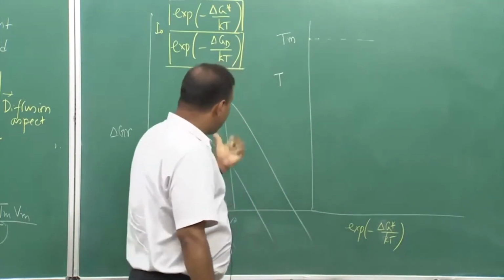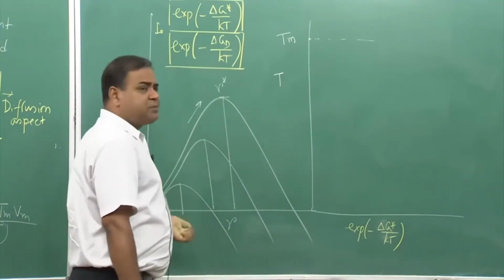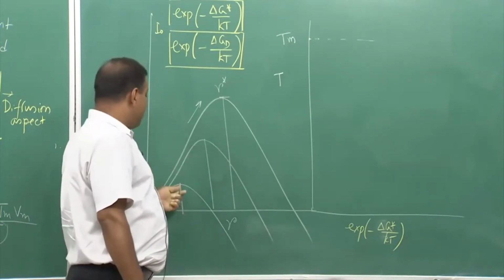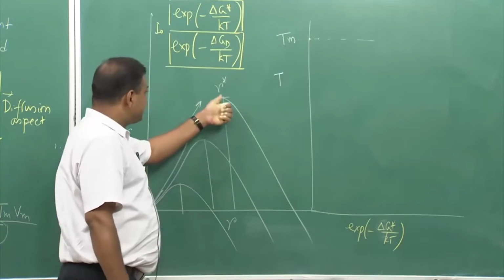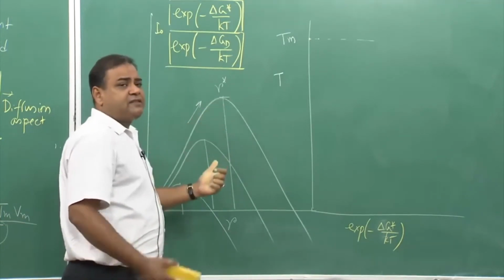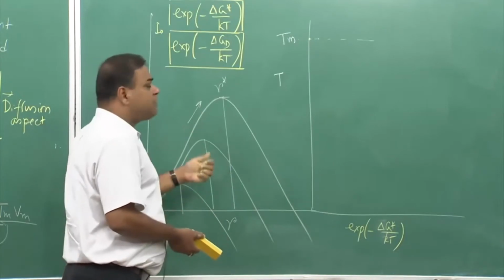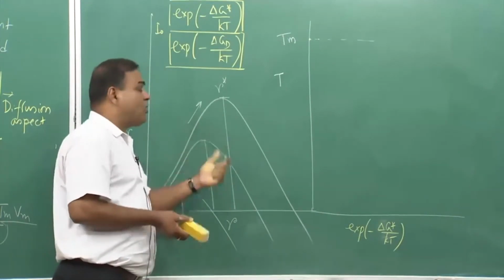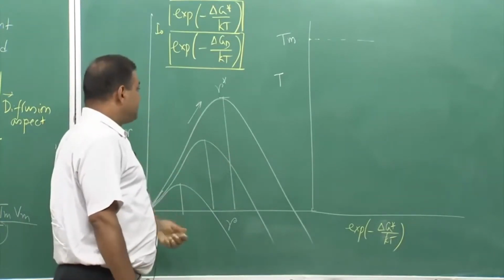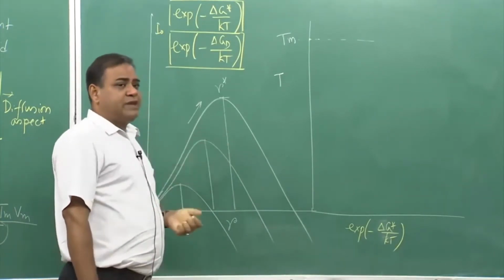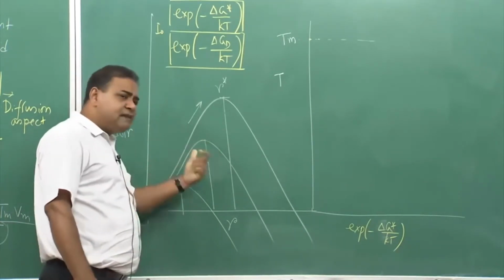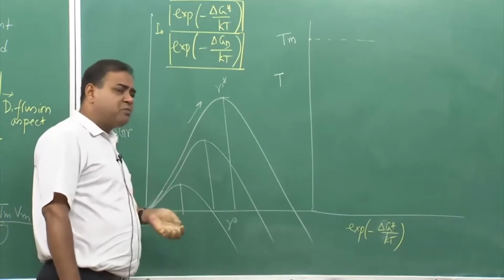Now, as we are going to lower and lower temperature and this nucleation event happens, going to the top of this particular peak takes thermal fluctuation. That thermal fluctuation will not be sufficient to form a very large crystal or very large solid. So, we need a little undercooling. Even if we have a sufficient undercooling, we will see that still the R star would be very large, still it is not possible.